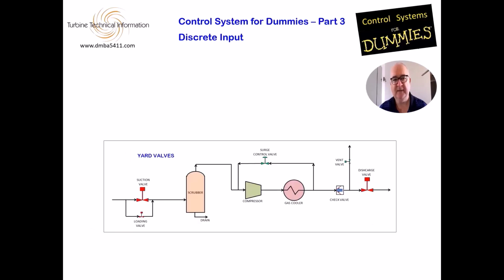When a compressor set shuts down, it will need to vent the gas that is between the suction and discharge valves. The vent valve will not open until the PLC sees that the suction and discharge valve are fully closed by checking the suction and discharge closed switches.